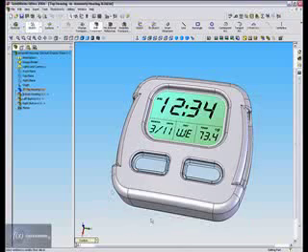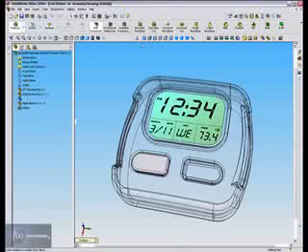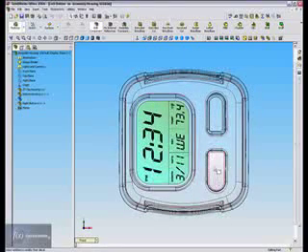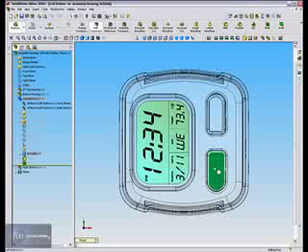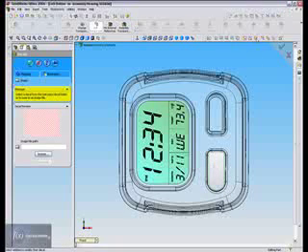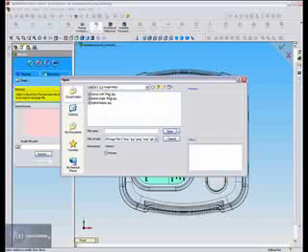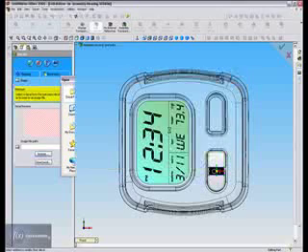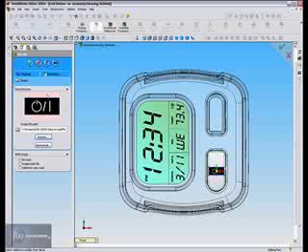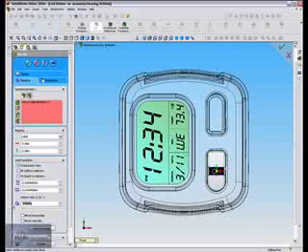Okay, now we'd like to apply a decal to the left button, so we right click left button, edit part. Again, I'd like to be in my top view when I'm applying decals. Select this surface and go ahead and select the decal button, and this time we'll select button left T-map. Open that, and as you see it's oriented wrong, so under mapping go ahead and enter 90 for that, and here we'll again go fit width to selection, fit height to selection. So as you see, this image encompasses the whole surface and it's dead on center.